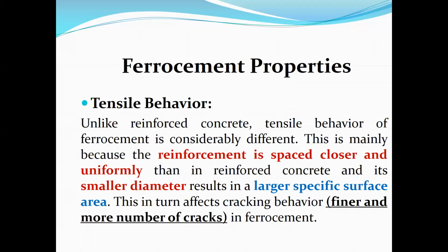Tensile behavior. Reinforced concrete tensile behavior and ferrocement tensile behavior are different, because in ferrocement the reinforcement is spaced closely and uniformly. Okay, and it has a small diameter. Small diameter means the specific surface is much higher. So the cracking behavior becomes different.